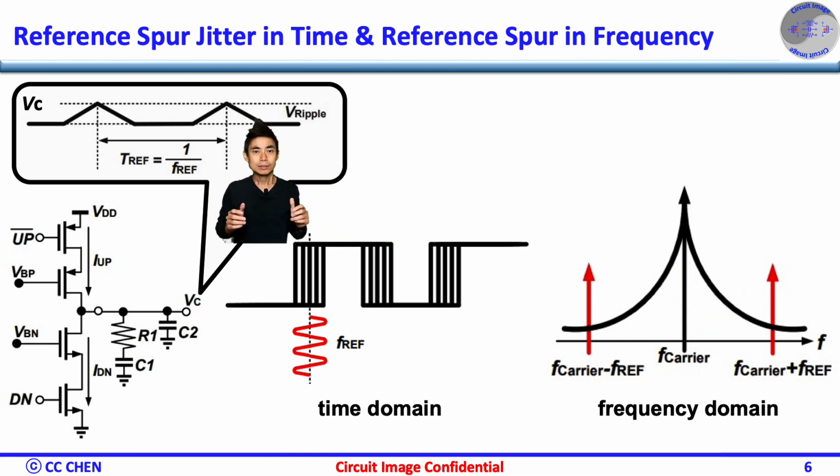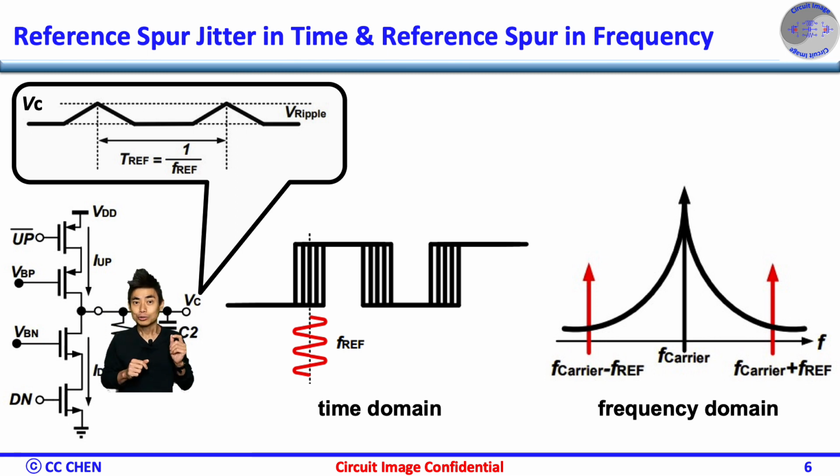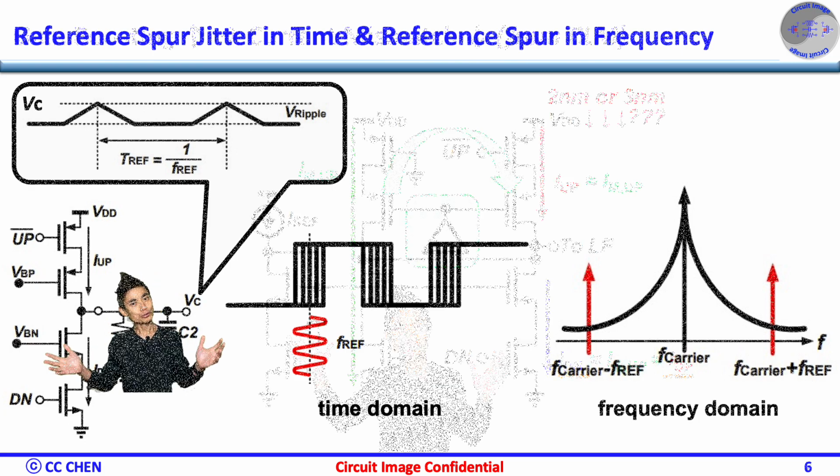As I mentioned, people spend lots of time improving the charge pump mismatch. Therefore, let's go through some of the previous works. The first one could be simply just improving the DC current matching. But we cannot add any cascode device since we don't have much headroom in the low supply and wide tuning voltage range. What can we do?